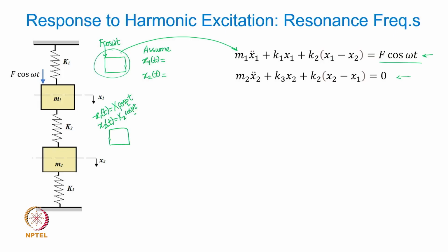With that, we obtained what? Mode shapes, natural frequencies. Here it is an externally excited system. It's not a naturally vibrating system. It's not a free vibration case. So what is going to be x1(t) and x2(t)? In here also, the two masses can have different amplitudes. Okay, what will be the frequency with which they will vibrate? We all know for linear systems, they will respond at the same frequency. They will oscillate with the same frequency as that of the excitation, right?